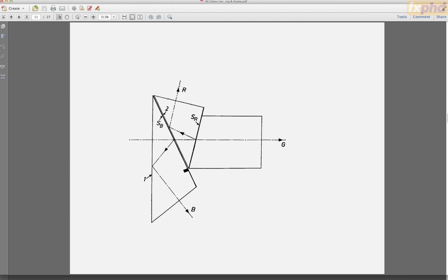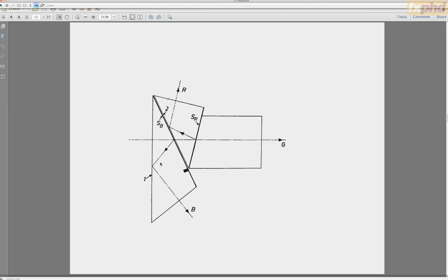So here's a slightly more accurate diagram of what's going on in the prism, and I show you this diagram to show you that here's the prism that separates out the blue. And so we're going to cement the blue CCD to this surface of the prism. So the filter separates blue here, but we use the prism to do total internal reflection. We don't need a mirror. And this is because you can arrange that the prism reflects, and it depends upon the index of refraction of the glass and the angles and so on. So there's very tricky optics that takes place.